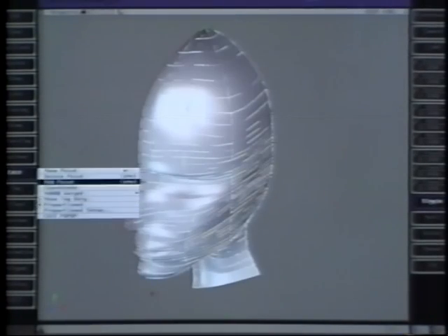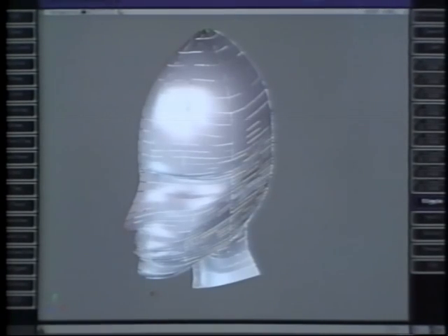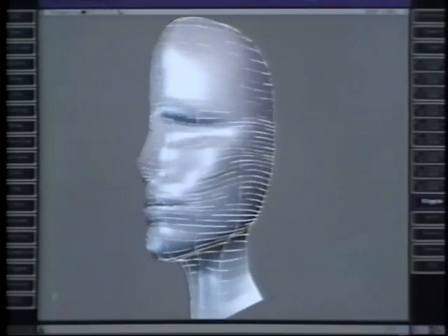From this framework, a process that can take several times longer than the original skinning operation begins, a process of adding edges and dragging points, often in proportional modeling mode, will move us towards a more complete surface.